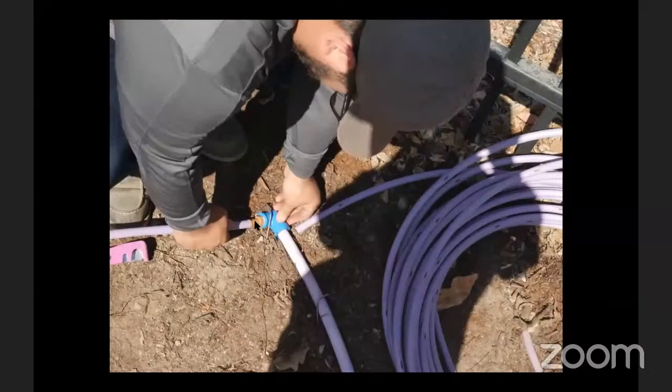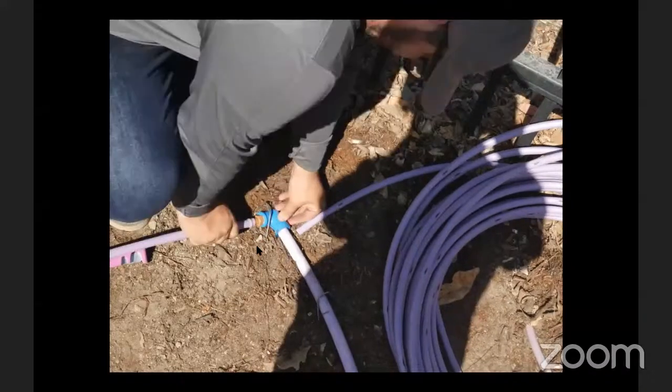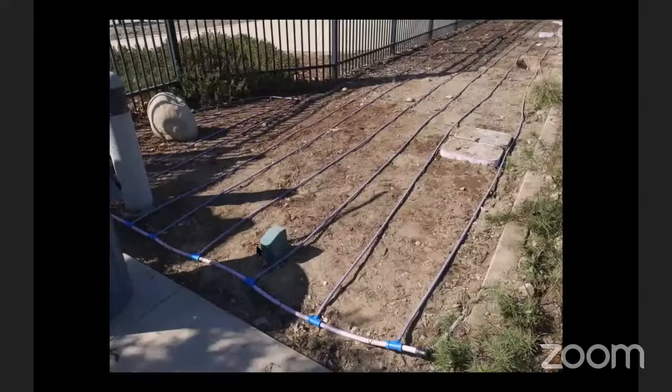And when you're pushing these onto the adapter, one of the reasons why sometimes you need to cut is because you need to make sure that you're pushing it onto the adapter at a place where there's empty pipe and not right on an emitter, because that emitter takes up some space on the inside and you can't push it in if there's an emitter right there. So you push it in, just kind of twist it on. And it's very easy on a hot day.